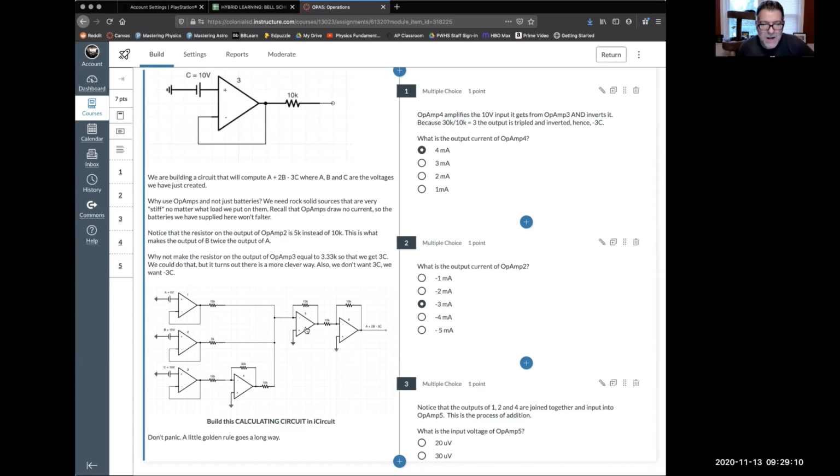And then all of that goes into this op amp, which is going to invert the signal. So this is basically my summing amplifier, the same way we learned about summing amplifiers early in op amps. I'm taking multiple inputs into the same amplifier. So here's a summing amplifier section, and then that signal comes out of the summing amplifier inverted. So I have to invert it back again.